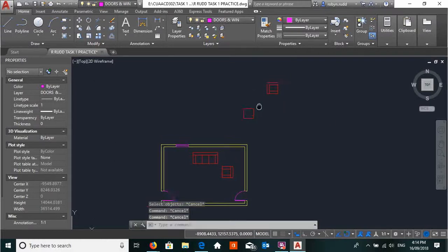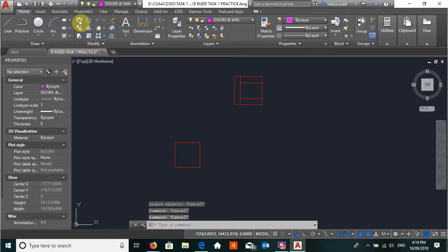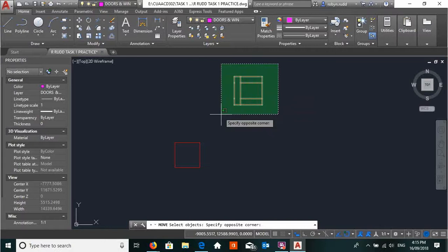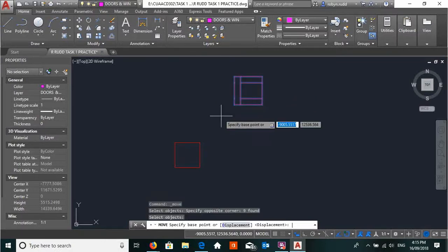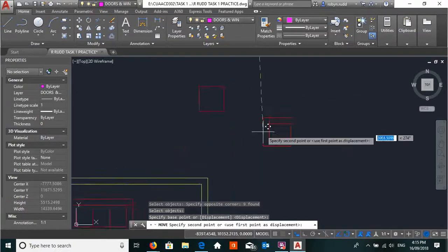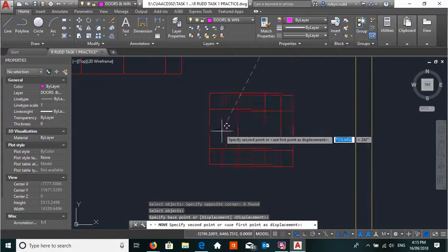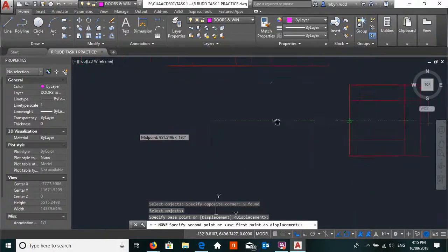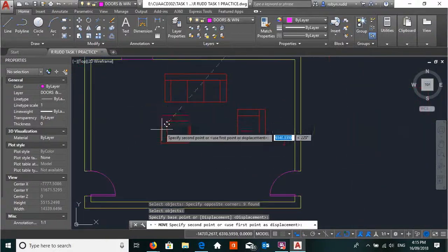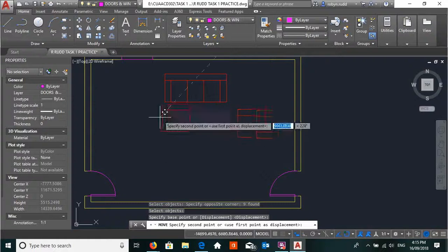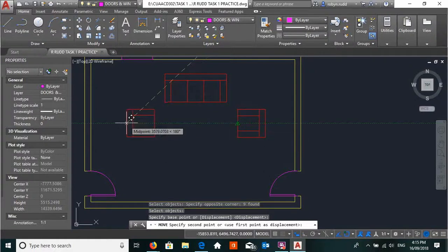Alright, again, let's just go through that again. Move, select move, click at the top once and click at the bottom. That is a green selection box. Click, press enter, select a point to move that, and then move it in line so that it works with this line here. Alright, so they line up. There we go.